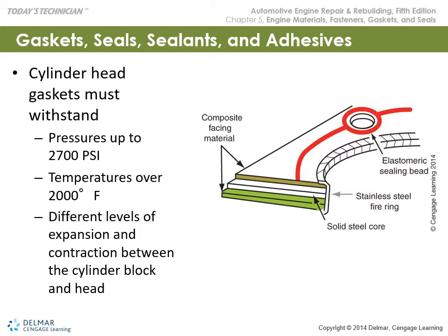Some head gaskets have a time limit. On some of the Duramax diesel head gaskets, you have about 15 minutes to set it up. If you can't torque it within 15 minutes, you have to take it apart and do it again. So GM includes 2 gaskets for the Duramax cylinder head.